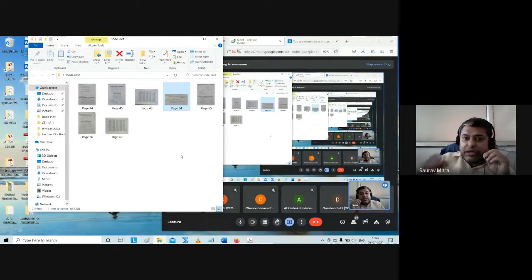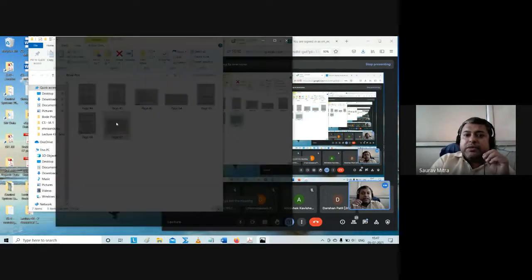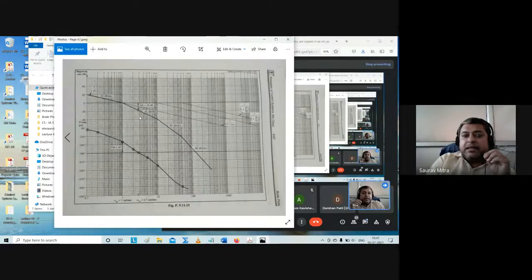Initially in our case, where we did not consider the value of k, the gain margin was plus 20 in this numerical. But what the numerical asked initially is that I want a gain margin of plus 10. That means you can shift this resultant graph 10 dB higher. That means you can keep the k value as 3.16. If you do not consider k, you get this, and if you take k as 10, you find this.